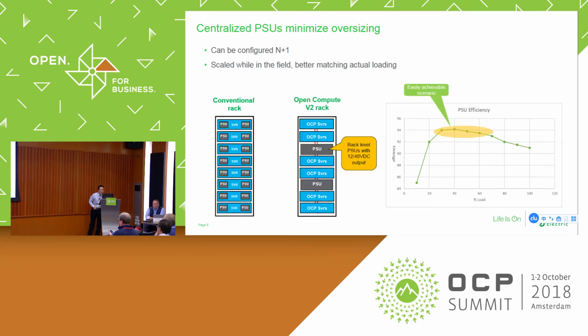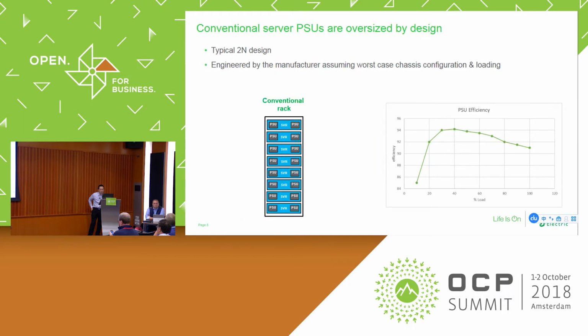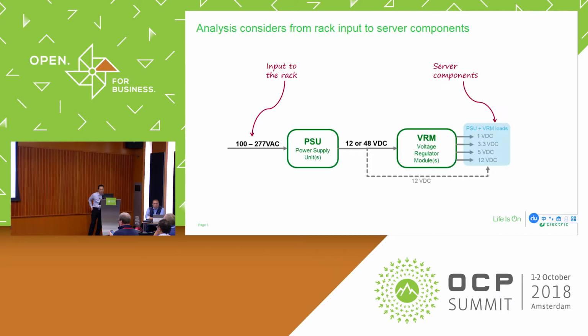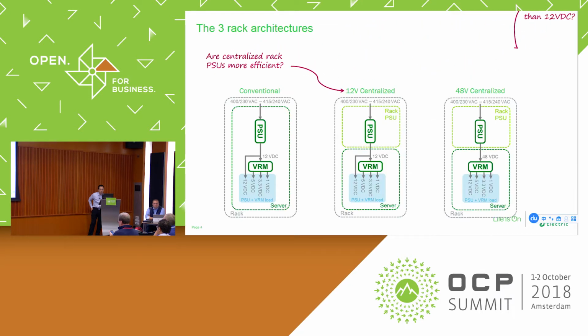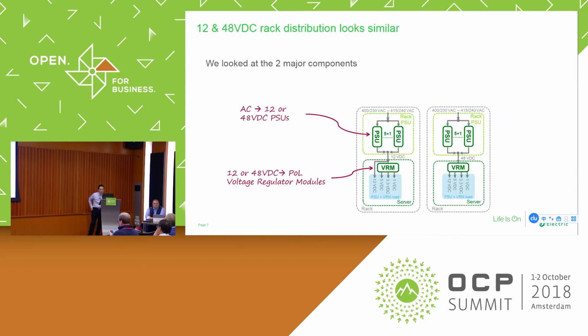One of the reasons we didn't include the bus bar is because you can size the bus bar. We didn't want to throw a bunch more assumptions into the study, so we just left it out. If it's sized properly, there will be losses, but they're reasonably minor compared to the component losses.